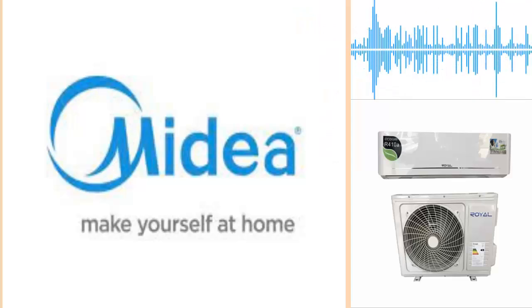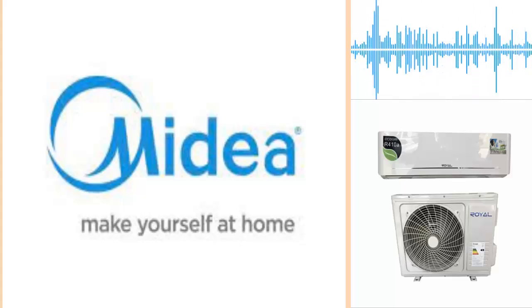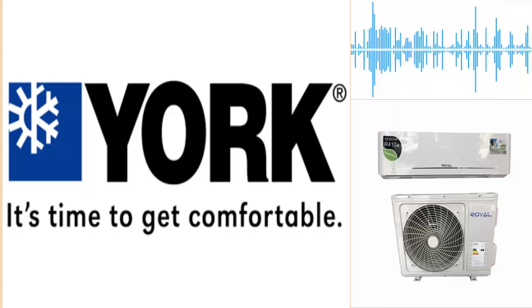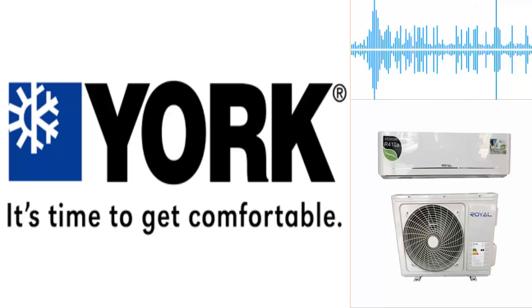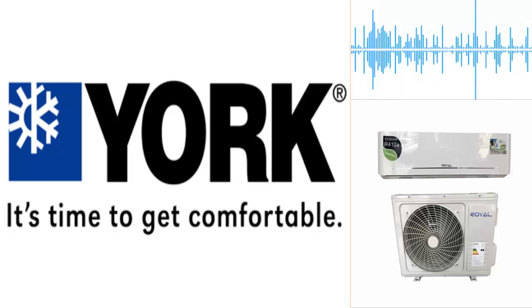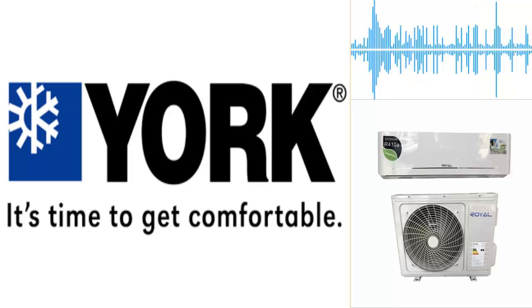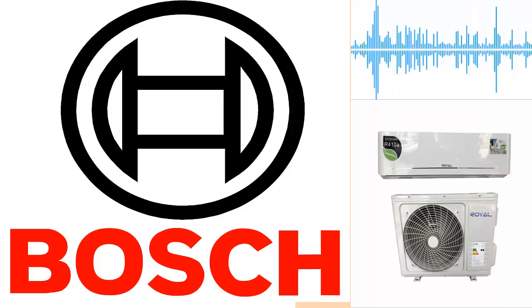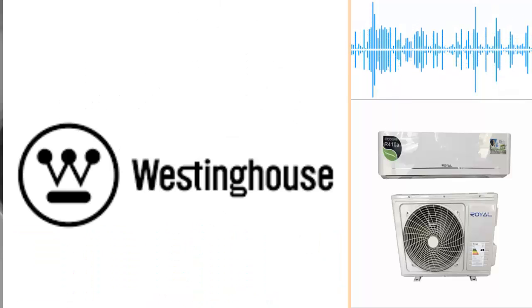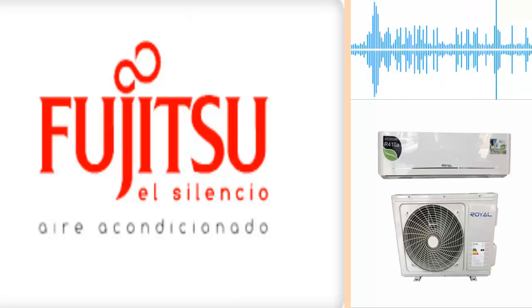Midea: issues with the outdoor unit's temperature sensor. York: issues with the indoor ambient temperature sensor. In central type York air conditioning units, there may be issues with the temperature sensor in the compressor discharge tube. Bosch, Westinghouse, Fujitsu: issues with the indoor ambient temperature sensor, with an open circuit or short circuit.